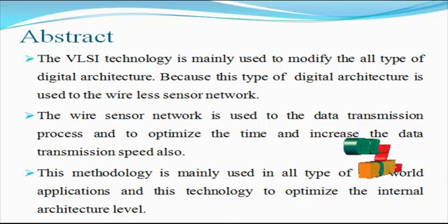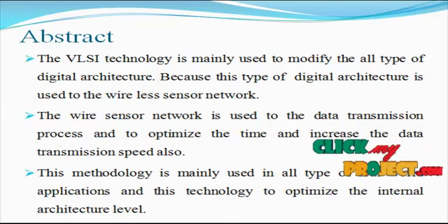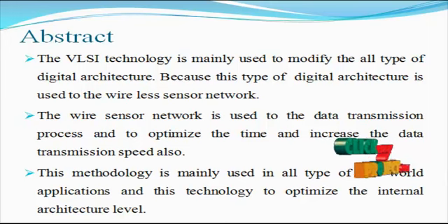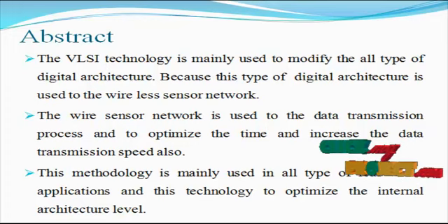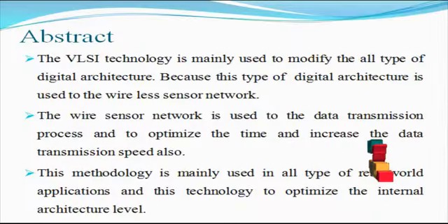Since radio transmissions are very expensive in terms of energy, they must be kept to a minimum in order to extend the node lifetime. The radio communication to computational energy cost ratio ranges from 100 to 3000. So data communication must be traded for on-node data processing, which in turn can convert many sensor readings into wireless sensor network information.